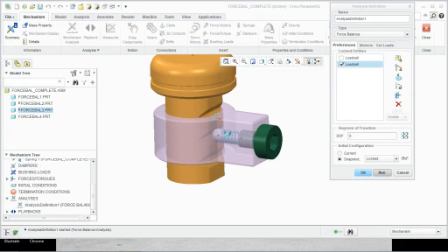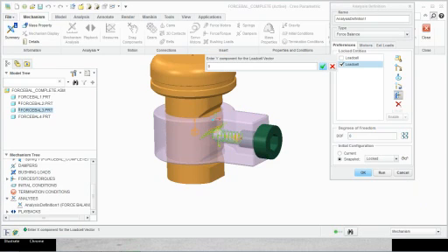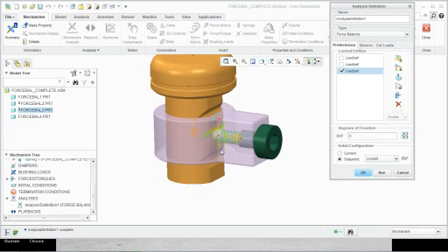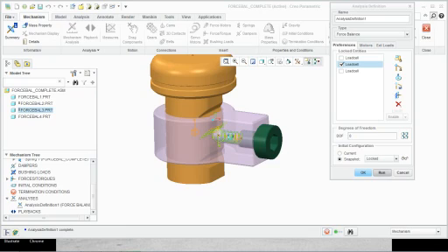Now, you can also say new load cell, same point, same body, but I want to know the reaction force in the X direction. So X is 1, Y is 0, Z is 0. And then I rerun it. And notice the value that I get is nothing, because there is nothing acting in that particular direction. So depending on different load cells in different directions, you can tell the force. So now I can say I need to push this ball inside here by 121 newtons so that this doesn't move.